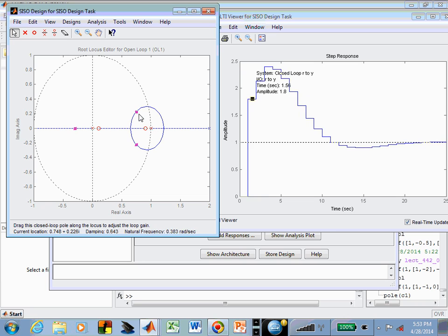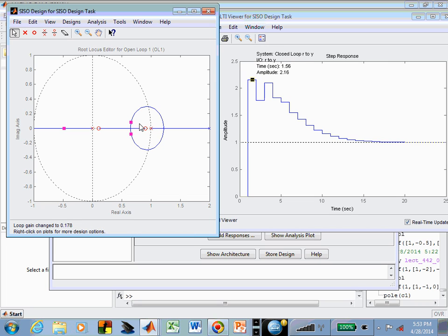Or now you've really increased it beyond 2, so now you might say, let me make that be my biggest value of my output. And you now crank the gain up a little bit, and this gives you a little bit of a feel as to what's going on between your poles, zeros, and gain value in the root locus.